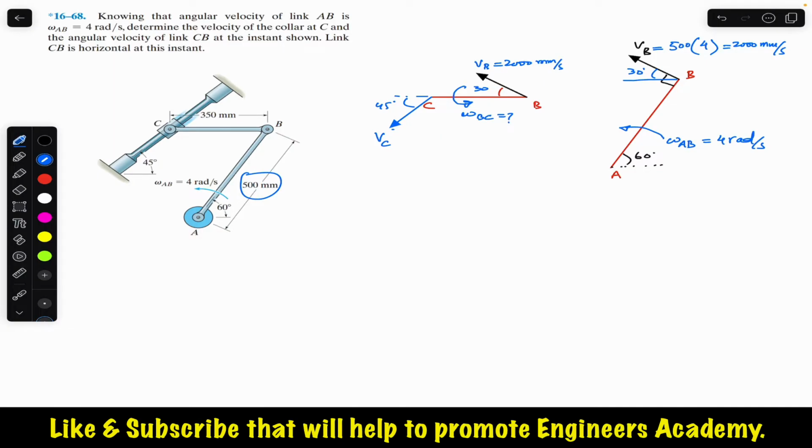We can say that the velocity of C is equal to the velocity of B plus the velocity of C relative to B. We are going to apply the vector equation. Now the velocity of C has two components, right? So we need to write all these three in vector form. So we need to write VC as a vector. VC vector is equal to, so now as we can see that this VC is making 45 degrees, it will have one component in this direction and one component in this direction.